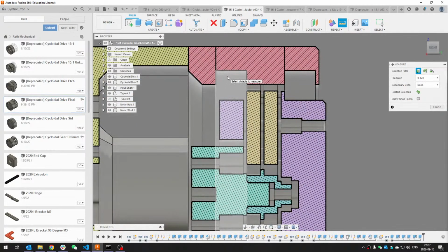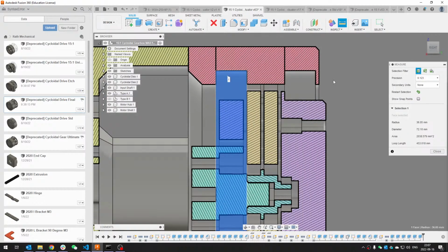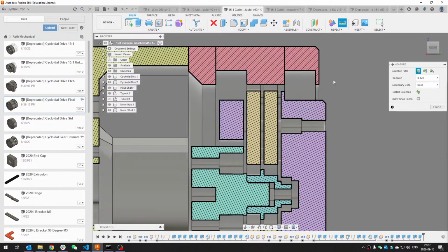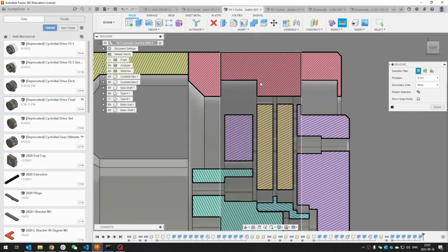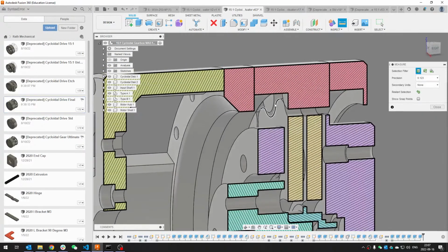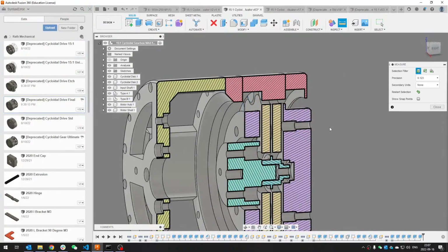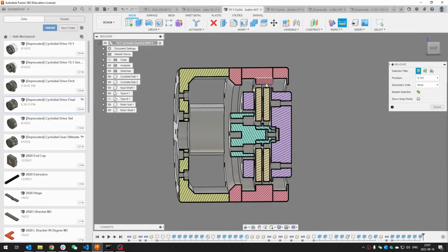And also if we can somehow find a thinner bearing for this one, it can be further decreased. Okay, but the limiting factor is the teeth here, because we need something to press against the bearing. So we cannot change this much.